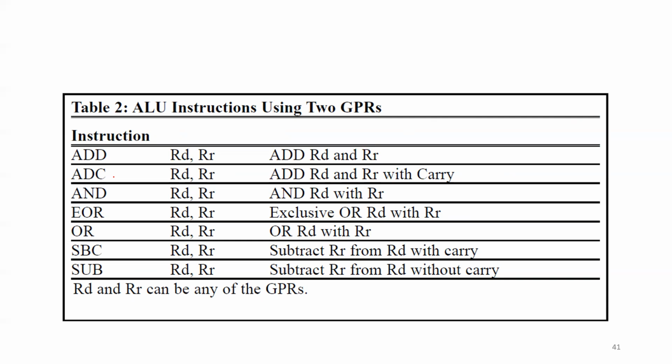Now, guys, if you have data of 8 bits, and you know all of the registers in the AVR microcontroller in our family now, which is the 328, it's an 8-bit processor, which means all registers and all memory location data are 8 bits or 1 byte. So what will happen if the summation of two numbers is greater than 8 bits?